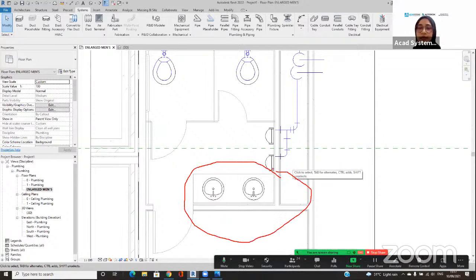All right. Another solution for when you are dealing with the architecture model here, this one, we're going to see for the thing here. What we can do is actually edit this family and then add the connector. The very tip for creating the pipe here is that it needs to have the connector. As long as it has the connector, you can model those pipes.